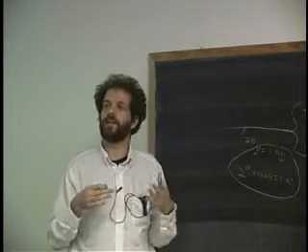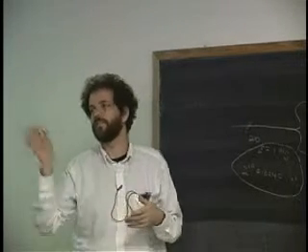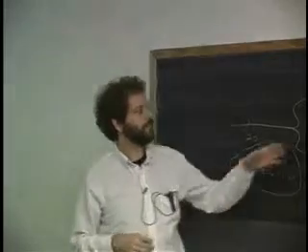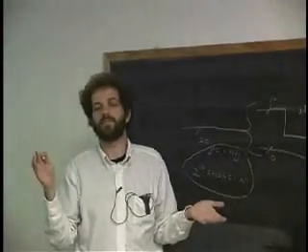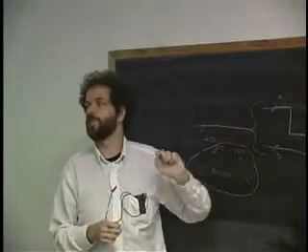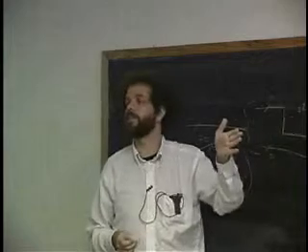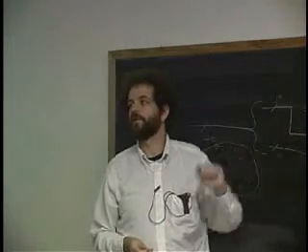Okay, it's not quite at 4 gigabits, but it's getting towards there. And so in another 5 or 10 years, it'll be 16. That's how much memory, because we have 2 to the 32 different places that we can access. So if I wanted to implement the entire big slow memory with 32 of these planes, each one would have to be 2 to the 16th by 2 to the 16th large. Okay?